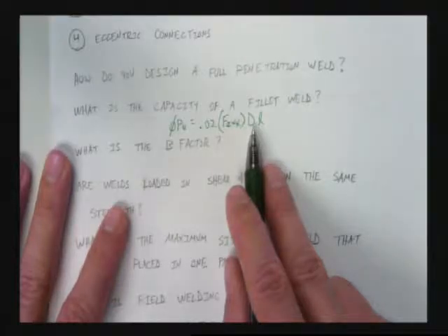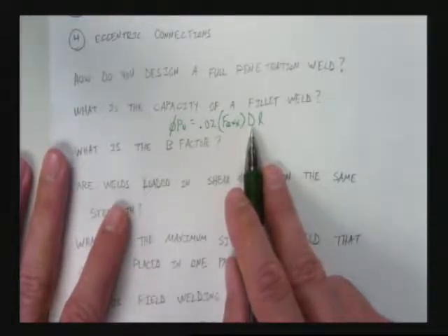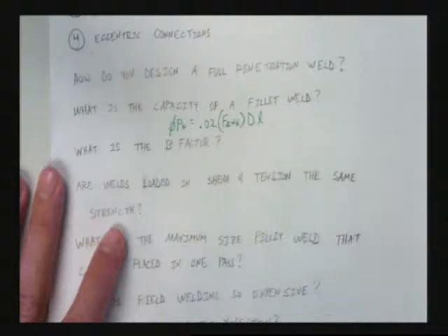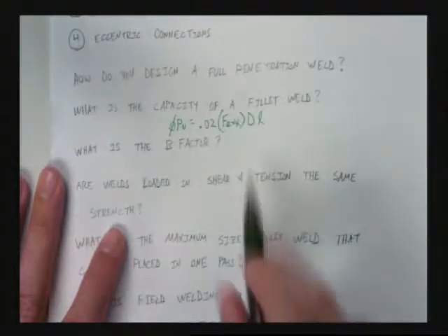This is also assuming an equal-legged weld, which I highly recommend you always use. Okay? Not saying it can't be done, but there's a lot of weird fatigue issues that people often ignore or aren't aware of when they use a non-equal size leg height. Okay? Okay, so great. Yeah, that's the leg height, 1/16 of an inch.